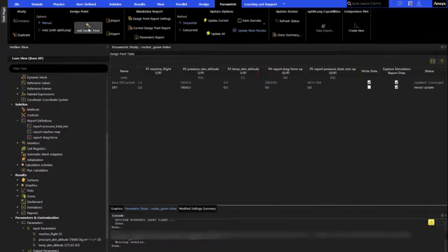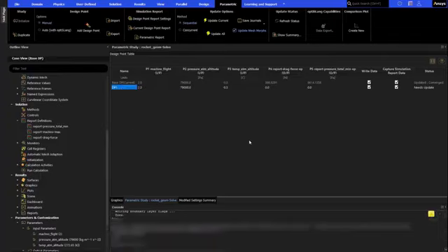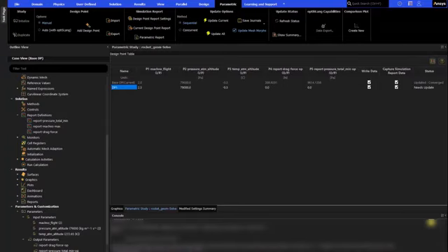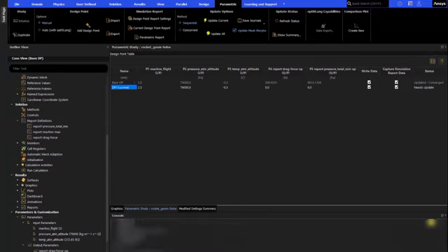Design points can be added to the Parametric Study table and the input parameters modified to represent different flight conditions. For this study, we'll increase the Mach number to see the change in drag at different speeds while maintaining the same altitude. Enabling the Write Data option will retain the simulation data if you wish to reopen a specific case for inspection later. To run the added design point, set it as the current case and select Update Current. In the background, Fluent will create a new case file, update the modified input values, initialize, and run the simulation for the selected design point.